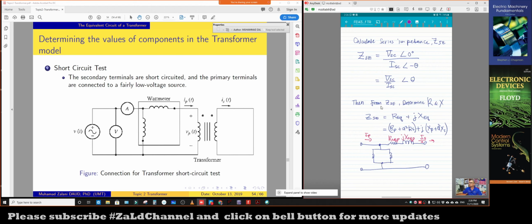Okay, so then from ZSE, we can determine further the series and parallel impedances, which is R and X. From ZSE, we can convert this polar form into the rectangular form. Then, for example, if you want to represent the equivalent circuit referring to the primary side, we can use this equation, where we use the turns ratio to convert this into REQ and XEQ.